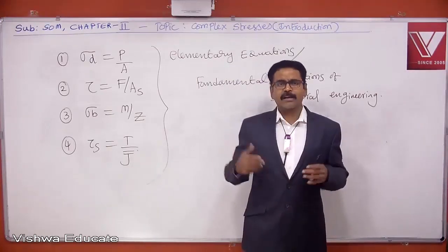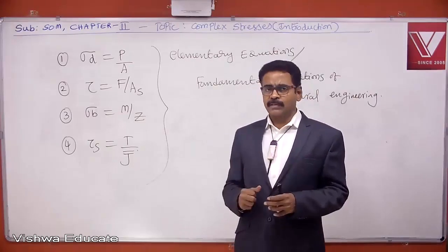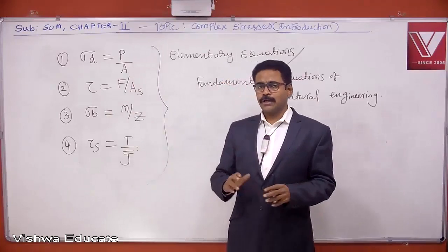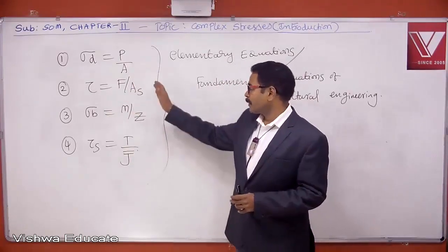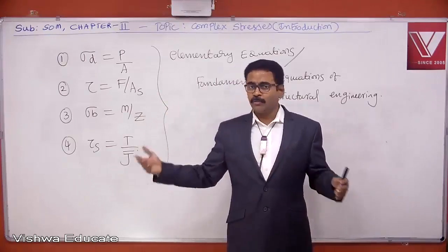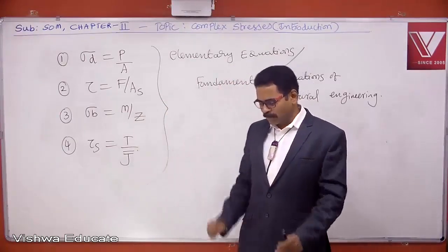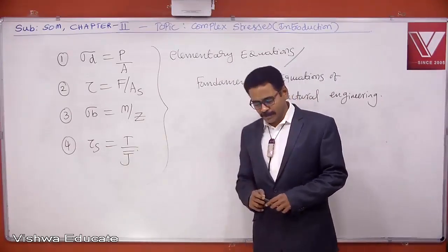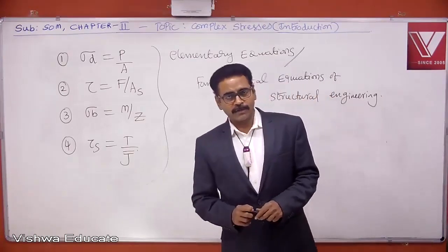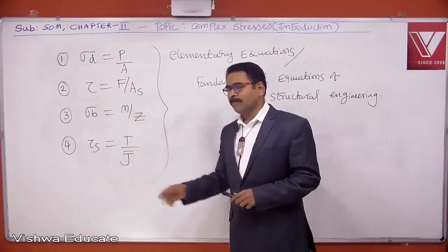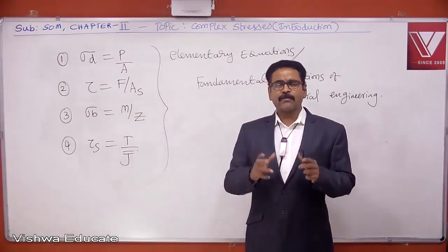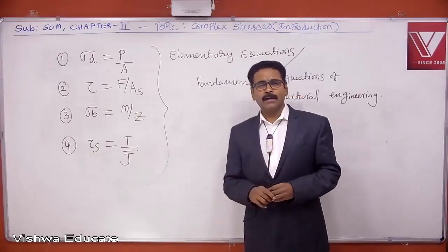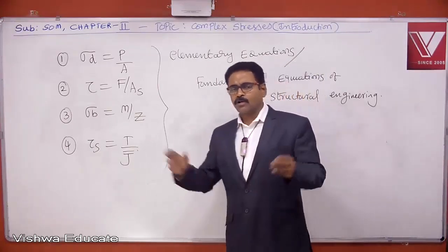So these 4 formulae are giving the response to the 4 basic loads. For example, if you apply a normal force, what stress will induce? How much stress will induce? If you apply shear force, what stress will induce? How much? Similarly, if you apply bending moment, what stress will induce? How much stress? Similarly, if you apply twisting moment, what stress will induce? How much stress? These four basic equations are giving all these things. They are dealing with four basic types of loads and their response. If you apply a particular load, what will happen to that structure? What stress may induce, and how much?